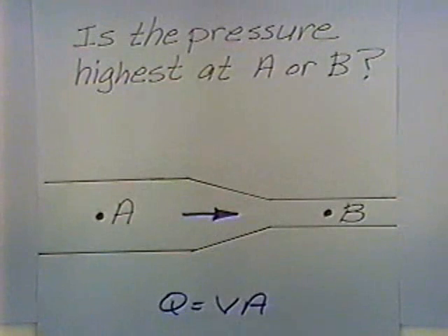And so the flow rate's constant. There's no change in storage. It's just a pipe. Continuity says a constant flow rate. And so the pipe gets smaller. What's got to happen to the velocity? If the pipe gets smaller, the area gets smaller, so the velocity's got to increase.